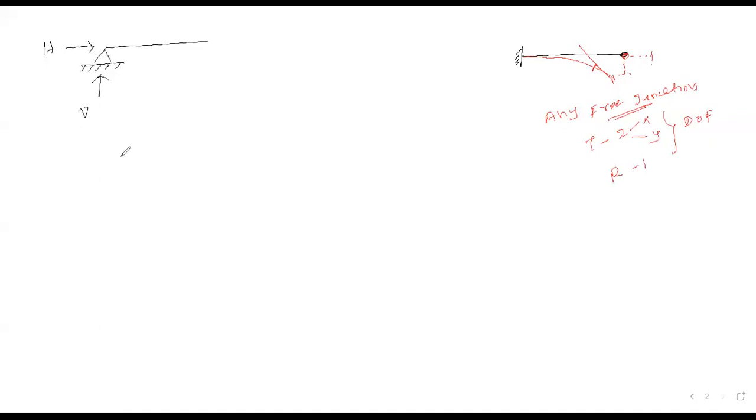Fine. Why I am discussing this will be discussed later on, don't worry. Similarly, suppose I am considering the roller support. Such a support consists of only 1 reaction, vertical. Fine. Now, this is not an exact definition. Suppose I am providing the roller support like this. In this case, your roller support will carry a horizontal reaction. Agree with me? Please confirm. If I provide a roller like this, there is a junction like this, and the member is provided in this way. So in case of the roller support, basically the reaction is perpendicular to the surface of the support.